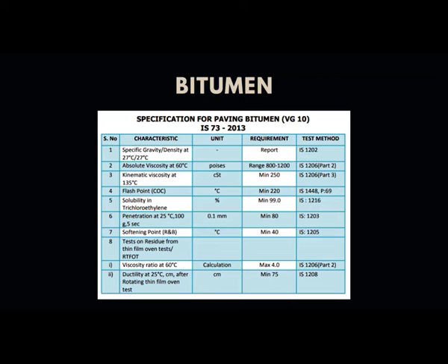So here the important tests for asphalt are the kinematic viscosity, then the penetration index. Penetration index is going to determine whether the asphalt can appropriately be used as an effective paving material. Then of course ductility is also an important test. But in a refinery, whether it is a key test or a less important test, every test will be done in the quality control lab, because every test has some significance from the customer point of view.